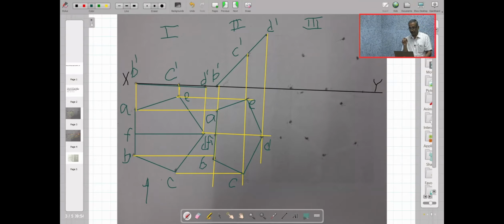The important point here is this line FD, which is in true length in stage 1. By this tilting, its length is reduced in the top view. When the length is reduced, what we are getting here is only the apparent length. So we cannot tilt the apparent length to the true angle. The concept is we have to find out the apparent angle. Let us follow this process to find out the apparent angle.